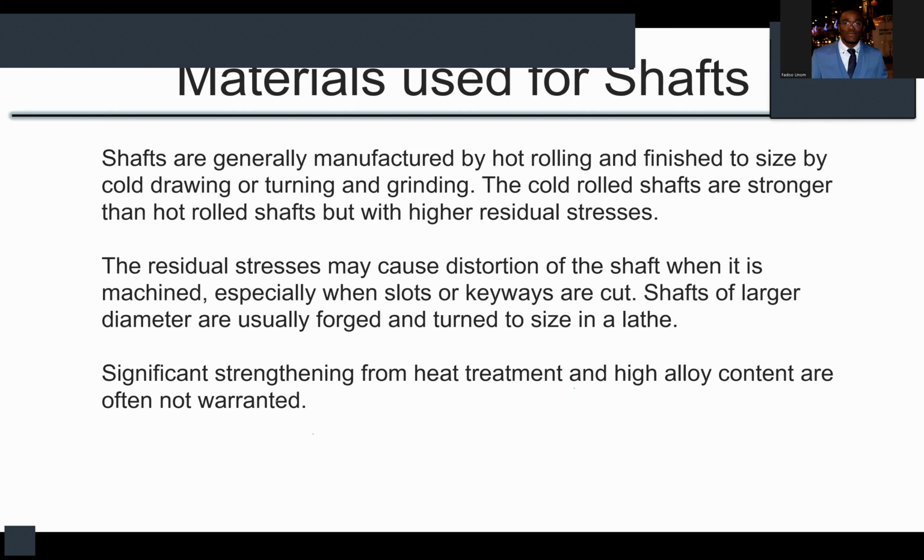Okay. So you see the effect of residual stresses. They may cause distortion to the shaft when it's being machined. They can cause problems when you are cutting in slots for your keyways. They can cause all of those problems.